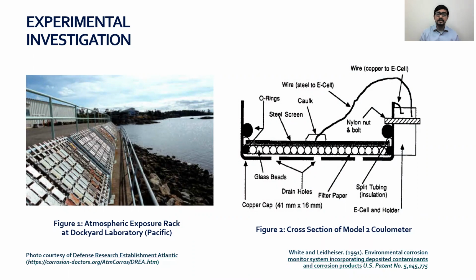One important thing about coulometer technology is that atmospheric corrosion is completely different to the wet corrosion environment. There is no long-term, continuous, ion-conducting liquid electrolyte phase that could be monitored using the conventional electrode system. That is why a thin film electrode is used in the coulometer method.